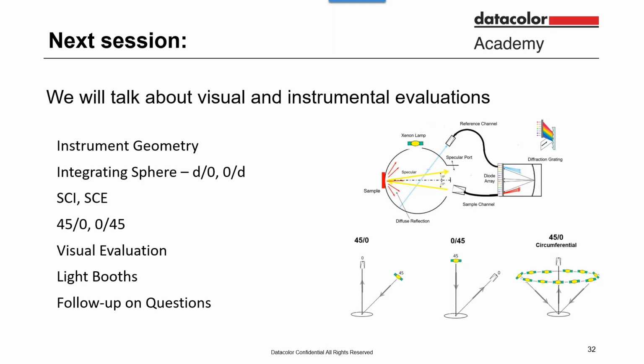A lot of times there may be a region, like a check, a visual. Ellipsoidal tolerancing is like that a lot: if you're near the edge of the ellipsoid, you'll say check, because if you're 0.99 versus 1.01, why would you pass or fail on a number that close? So you may also have a visual check at some point. In some cases, you have to be under the number, and that's just the way the customer wants it. I don't know if that helped, but that's the perspective. And if you have any more detail, you can supply it on the question.